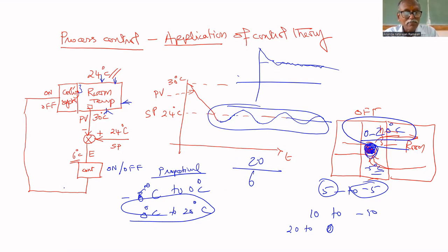That's why here the controller is changed to proportional only, P only. Depends upon the error, cooling element temperature will be there. That is called a proportional controller. That's why I'm putting P. I removed that on-off controller. I put a proportional controller. Still then you cannot make 24.